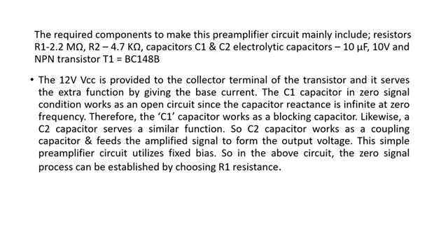So the required components to design this preamplifier include two resistors, two capacitors, which are electrolytic capacitors of around 10 microfarad and around 10 volt, and an NPN transistor that we use. For the power supply, normally we give the supply to the collector terminal of the transistor.